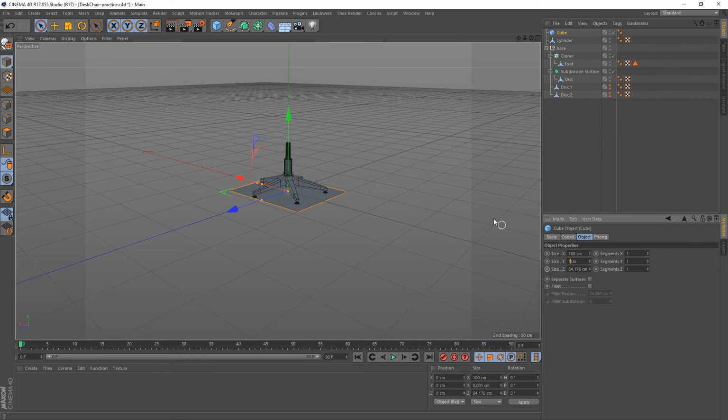Also, if you're in the X and you type 1 meter and hit Enter, then you can't go to the next field. You got to click in the next field. But if I type in 1M and hit Tab, then I can get 1M Tab, 1M Tab. That's the quickest way to go in between all of those different options.